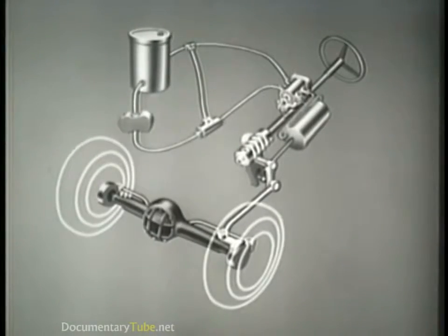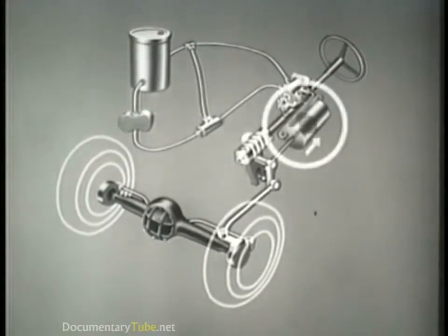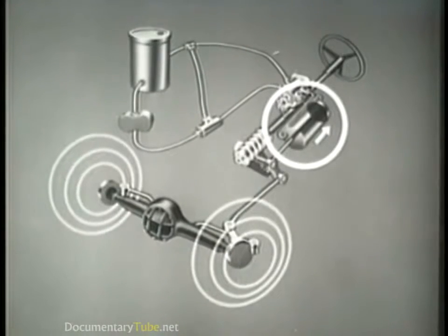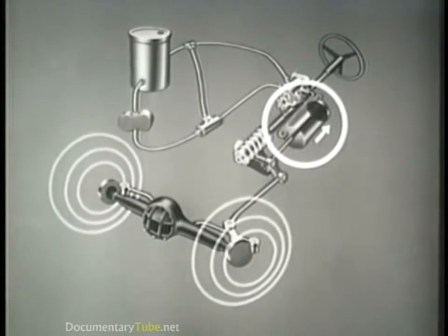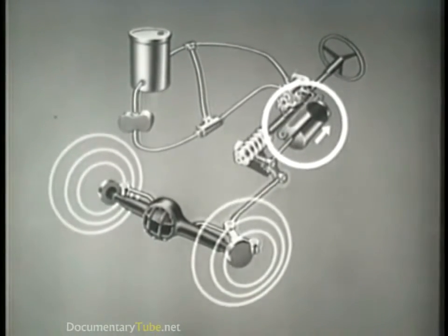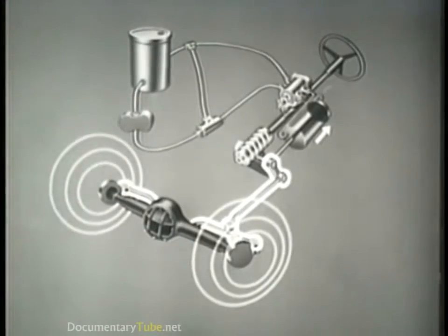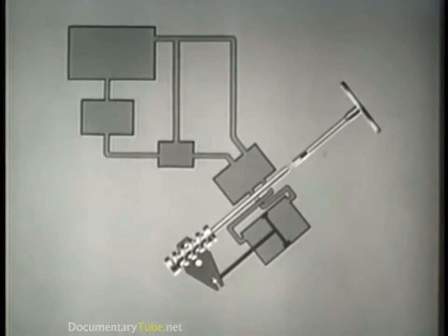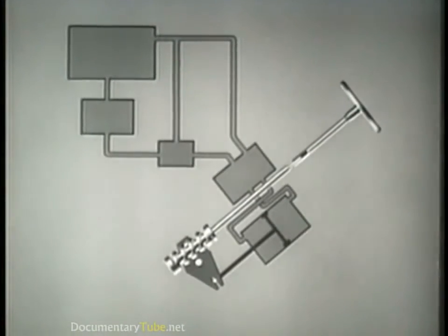In like manner, as the fluid pressure is increased on one side of the piston, the piston will be moved by pressure differential, aiding in steering the front wheels through the steering linkage. To aid in illustrating the internal function of the hydraulic system, a schematic diagram will be used. The steering linkage from the pitman arm lever to the front wheels will not be shown.